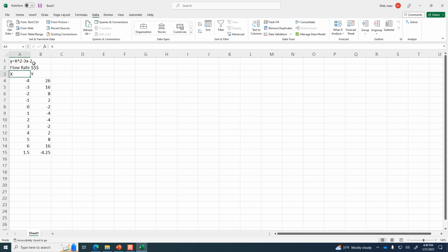Shouldn't the flow rate be equal though? Because you wouldn't want to pump more, like you just said, pump more water up. It's coming down. So. But it's a different number of hours per day. Oh, okay. Yeah. So it's 10 hours versus 14 hours. But you're right. You want the flow into the reservoir and the flow out of the reservoir to be the same. So if you've got 10 hours, your pumping flow will be slightly lower. It'll be slightly lower if you're doing it for longer. It's 10/14 lower.